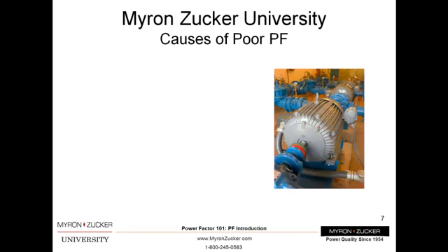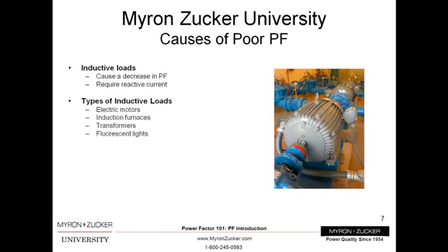So what causes poor power factor? Inductive loads cause low power factor because inductive loads require reactive current. Inductive loads include electric motors, induction furnaces, transformers, metallic ballast fluorescent lights, and compact fluorescent lights. Since 65% of the total U.S. industrial electrical consumption results from motor load, electric motors are the primary contributor to low power factor.